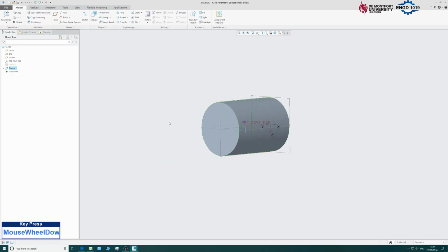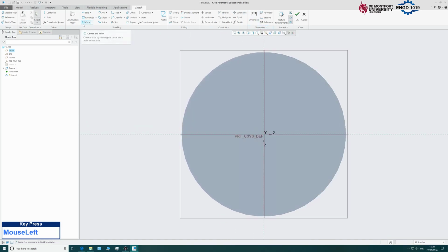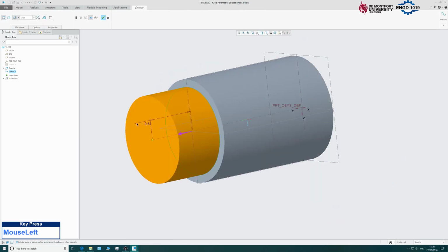Now the next section is an undercut section for the thread. So I'm going to build that up by drawing another circle. Extrude, click on this face, click sketch. Let's go to sketch view, and again we'll just use the circle tool. And the diameter on this one is 8.5 times 2. Okay. And again we'll use the extrusion, and this time the thickness this needs to be is 4, and we get that from 30 minus 26.